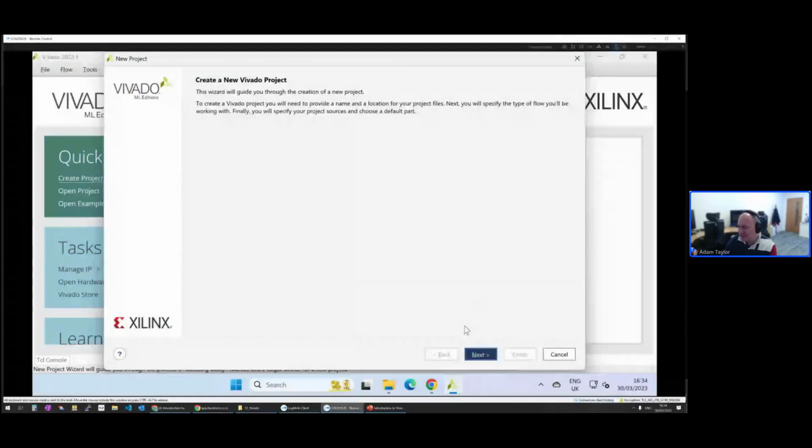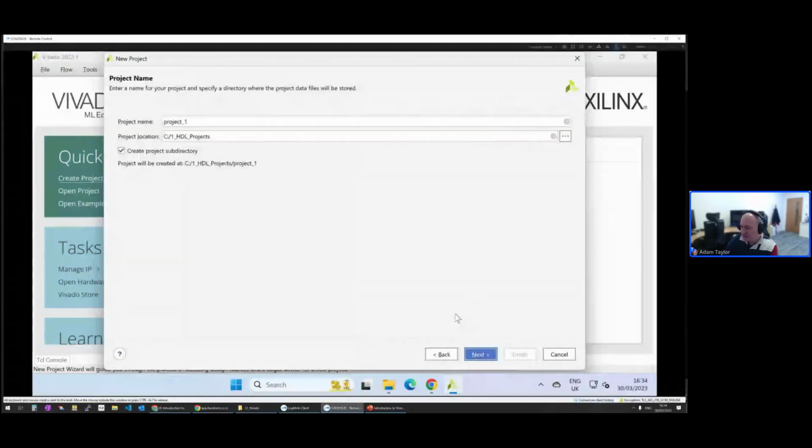So Carlos, that's an interesting question. Is the report CDC in Vivado comparable to commercial CDC analysis tools? It's a little bit of half of one, half a dozen of the other. The commercial CDC tools generally allow you to find it from the RTL, not from having to have done synthesis and such like first. And they can be a little bit more IP centric. So you can take whichever one you want.